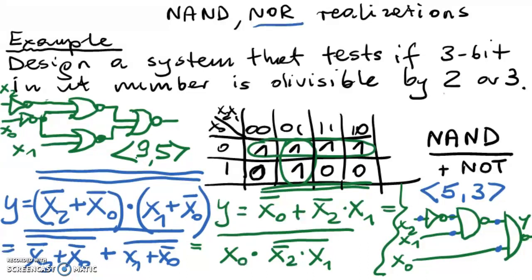But for our case, I mean for this course, we'll be using a very simple academic cost factor, only to compare the implementations. So do the same, the 2 minimizations, and remember, if you have a free choice, please minimize for ones if you implement in NANDs, or minimize for zeros if your implementation is in NOR gates.